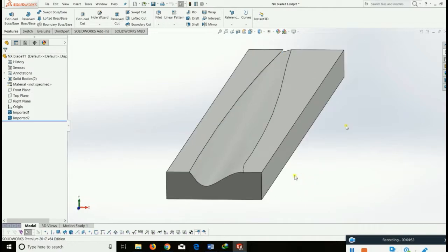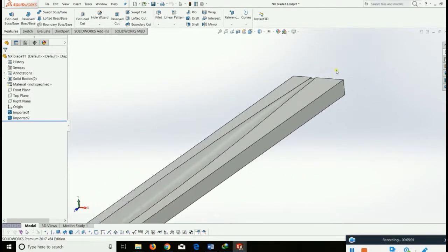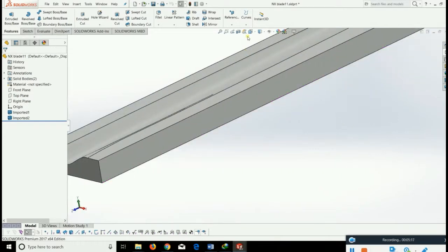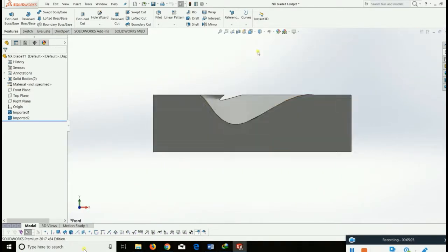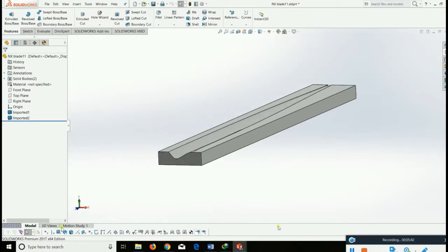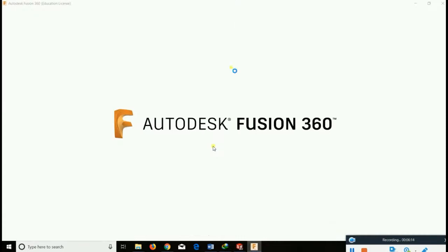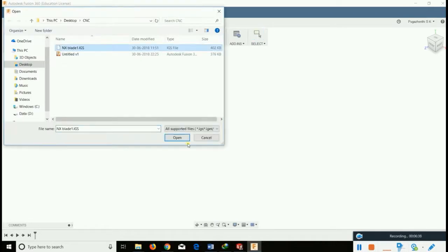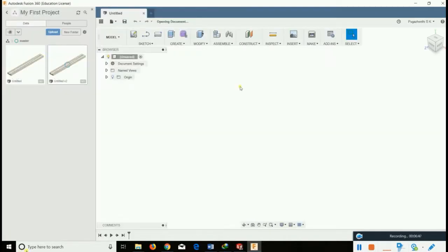Now we are interested in designing this turbine blade mold. For that we made a female cavity by generating the offset of the aerofoil section, and we created the extrusion operation. Then we followed the machining process in Autodesk Fusion.